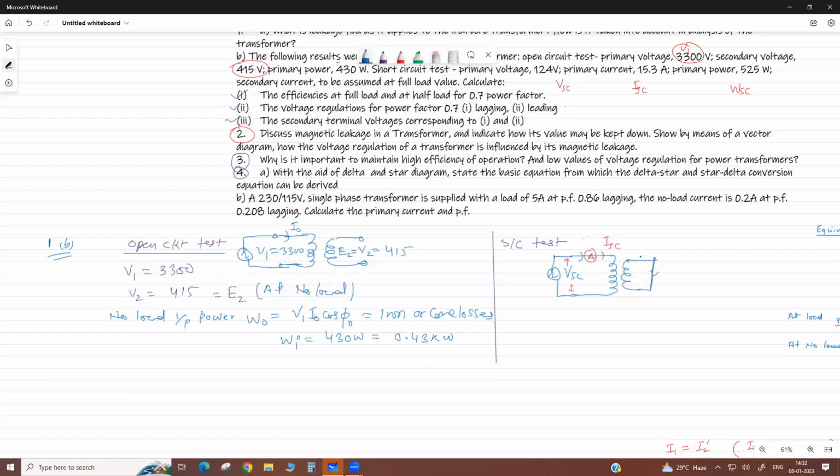Okay, dear. So here the short circuit current flows because it is short circuited. Then when your transformer ammeter takes a rated ampere, then we note down the rating. We increase the voltage till your transformer takes full load current. So here this VSC is applied voltage, under short circuit, what is the voltage?